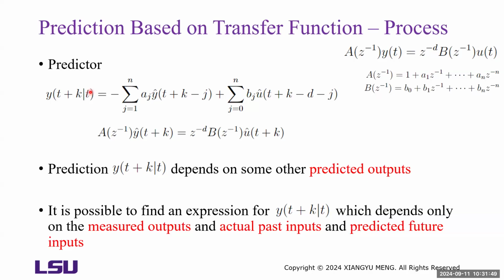So this saves on computation, which is particularly important in application to adaptive control, while the predictors, as well as the predictions themselves, have to be computed online. It also gave us some insight into the way the predictor design affects the predictive controller.